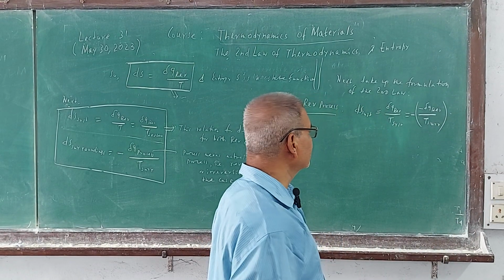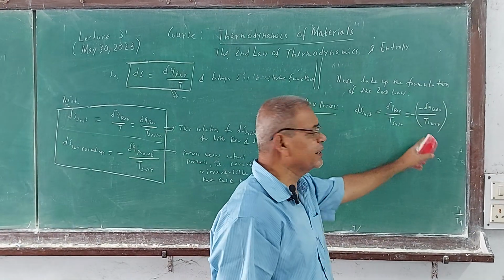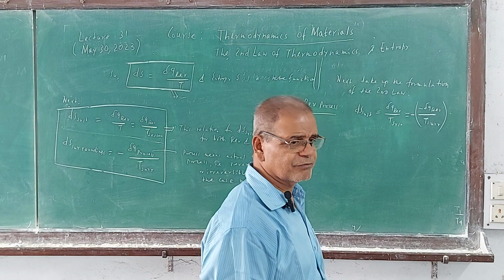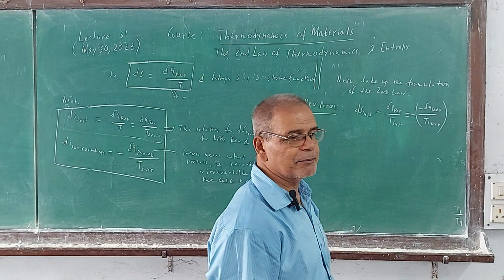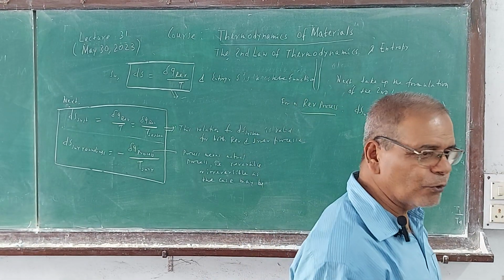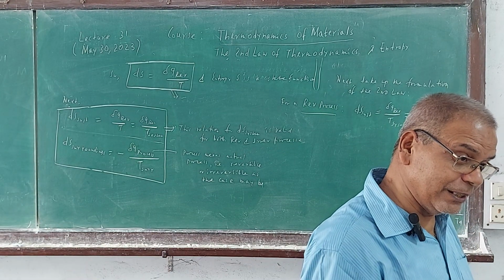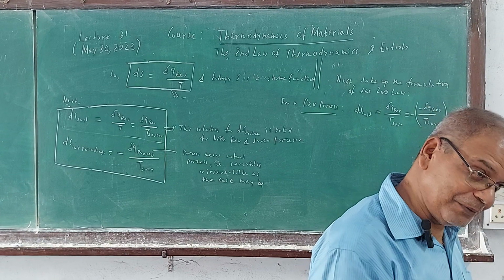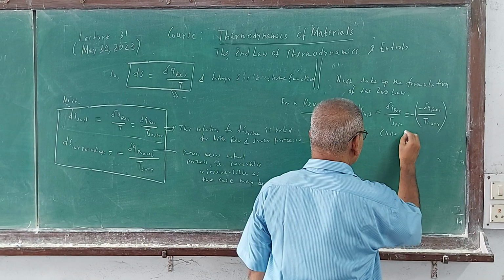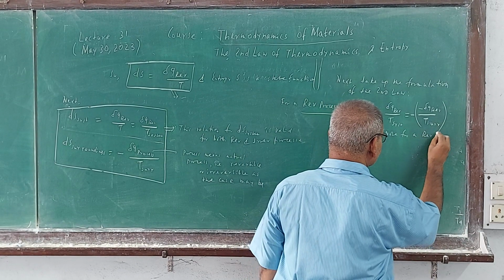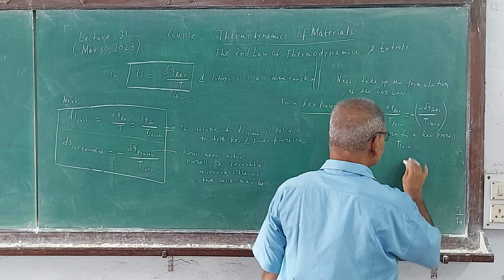Minus plus dq reversible in the numerator. T system and T surrounding, they are the same. Why? It's a reversible process. In any reversible process, surrounding and system temperature cannot differ by more than dT, meaning essentially the same result. For irreversible, there is a finite driving force; for reversible, infinitesimal. So write a note: for a reversible process, T system is T surrounding.